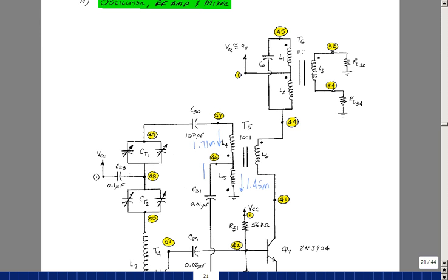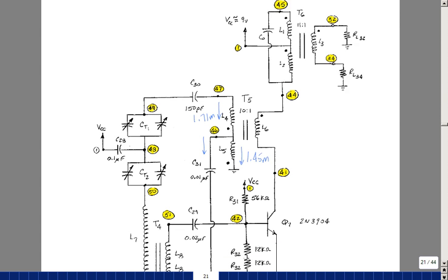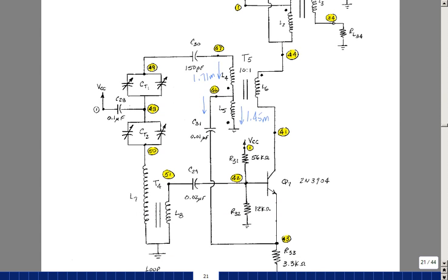That means that there's some current going down in here of the difference of the two, which is about 0.26 milliamps. That's exactly what I measure. Now, where does that current go? Well, the current comes down here, and it goes back in the resistor. It can't go back up into the transistor. And indeed, the current in this resistor is exactly the same value.